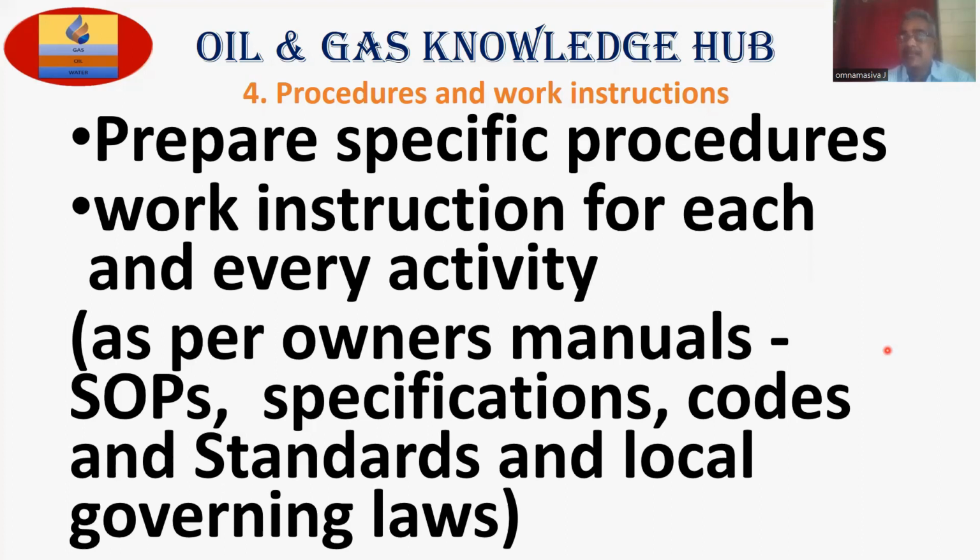shutdown activity, spades activities, P&ID walkthrough procedure, identifying the blinds, spectacles, reversal installation of valves, and hot bolting activities, procedure for hot bolting, replacement of gaskets.